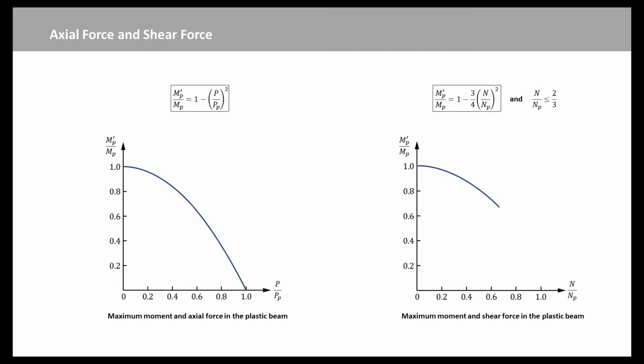From these figures, it can be seen that in low-rise structures, axial forces are too small to have any significant effect on the plastic moments. In high-rise structures, they are more important and allowance must be made for them.